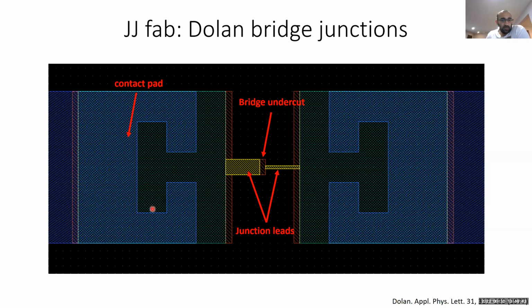Because you're doing an angled deposition, there's going to be a shift in the metal. So you also want a low dose exposure, given in red in these regions right here, to provide room for that shift to take place and to make sure that aluminum doesn't get deposited on the sidewalls of your resist.